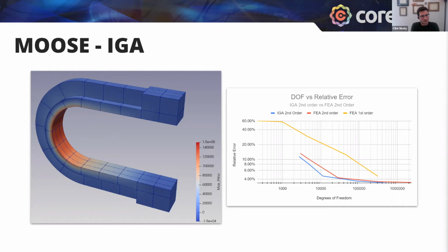If you were looking at this with the finite element, there are only 3 elements through the quarter circle, 6 elements through the entire bend radius there. It would not be a smooth transition with a FEA approach. So this is, again, we are capturing the exact CAD geometry as we are looking at here. And of course, this is a body fit geometry, so the fillets did unfortunately have to go away.